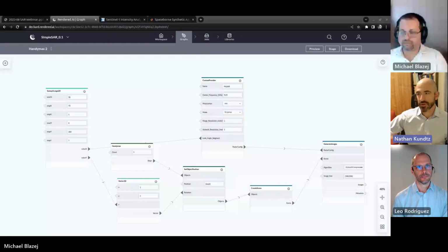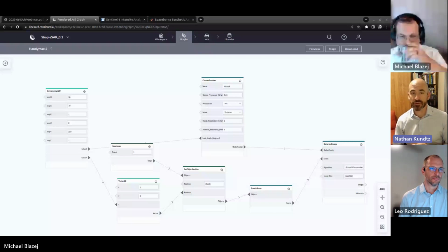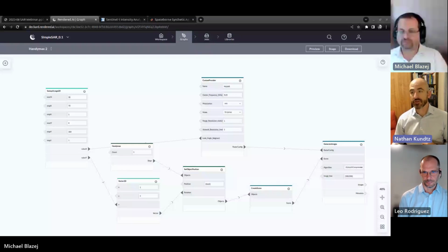The reason is what you're picking out is what's called the Bragg resonant reflections off of that rough surface, and we model exactly that. In fact, in the way that our 3D models are provided into the platform, each surface has a conductivity, permittivity, permeability, but also a roughness character that tells us how much of that Bragg resonant response to include for that facet.